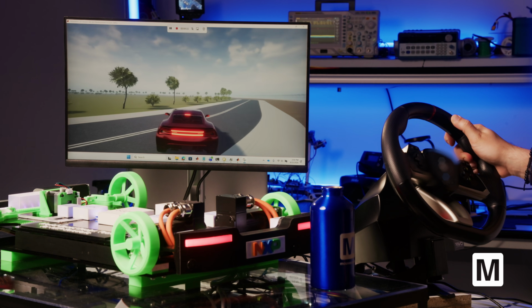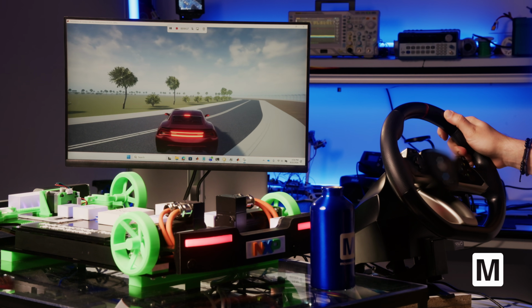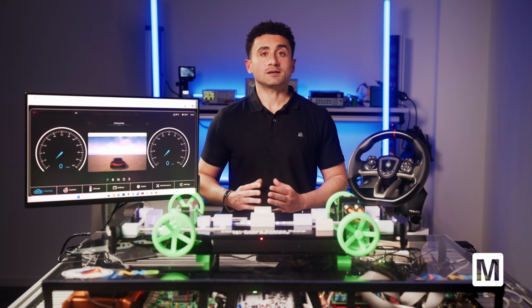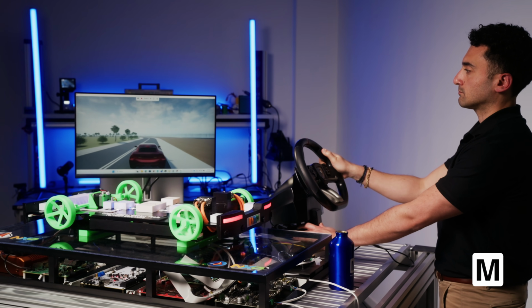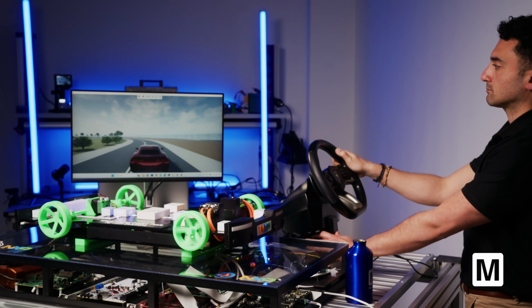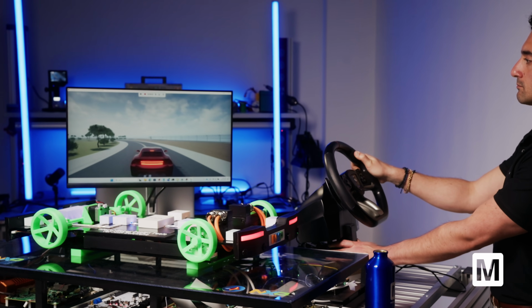The sensor threshold is crossed, the logic transitions to the braking state, the stop lights assert, which is visible right here on the physical model. The same state machine running on the S32K312, responding to a live simulation event in real time. Now let me walk you through how this is built.